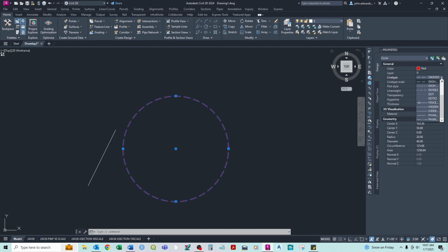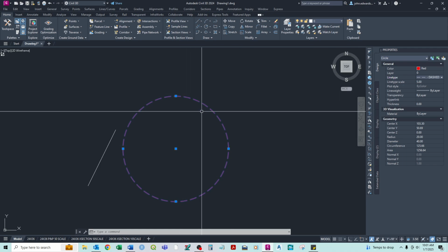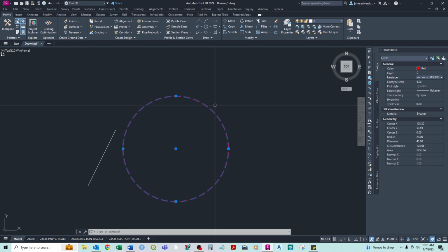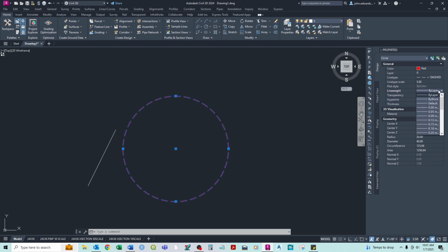Okay, so there's a lot of these. It would be good to just play around with them. This one's for fences, there's dots, there's all kinds of different ones. Okay, this is kind of a typical center line. Anyway, so that's built in there, and then your line type scale will kind of change the look of it and kind of the spacing of some of that. Okay, and we can change the line weight, which it generally doesn't show up until we print. So that one's a bit messier, but it's there. And transparency, again, it doesn't really affect it until it prints.